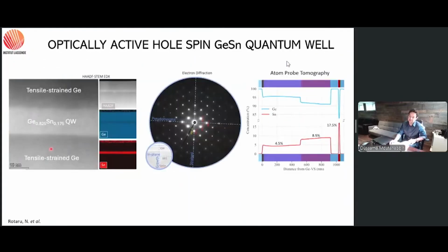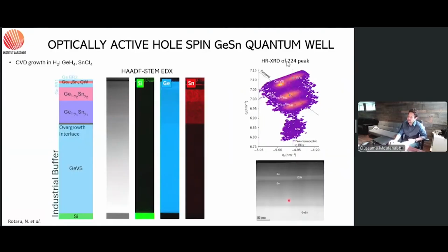So imagine you want to make a Hall bar in a heterostructure that is absolutely not yet investigated. Think about which dielectric. Dielectric is easy, but which side of the contact, how you can diffuse the contact. The thermal budget here is completely different from standard quantum wells like germanium, silicon germanium. So we're learning our way in just how to make the contact work.